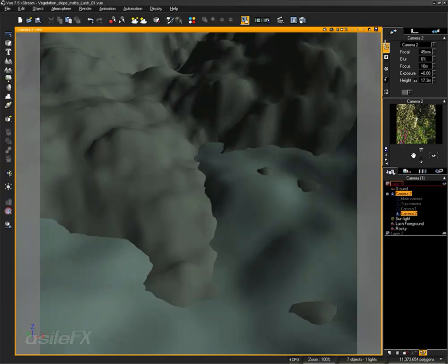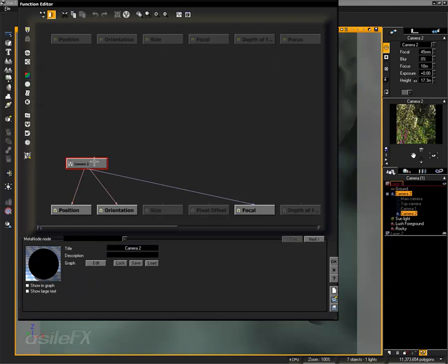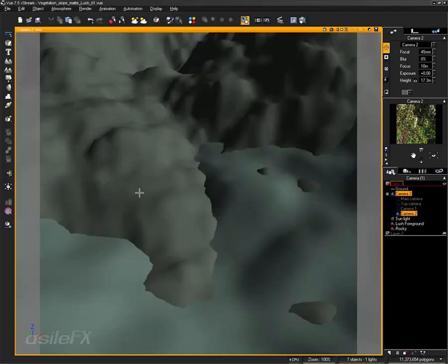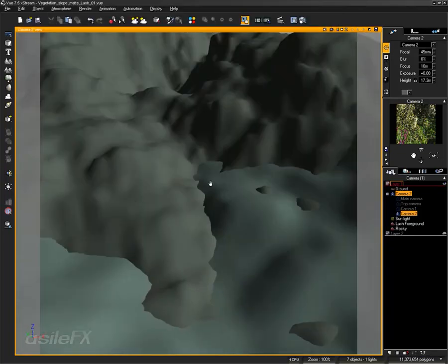Another thing is keep height lock off. We can see this will lock the height of the camera above objects. Make sure that's turned off because that can cause some errors when you're trying to manipulate things or when you're trying to keep the camera in a static place. I'm going to go ahead and just disconnect the metanode so I can free the camera.